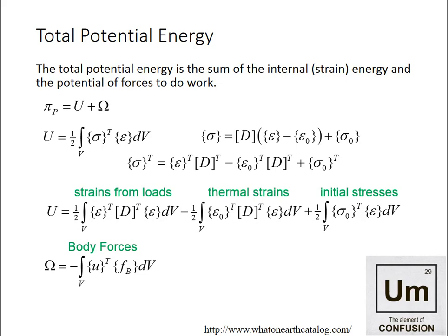What I'm going to do is break the forces into 3 different components. So the first one I've got showing here is the body forces. So I've got my expression for the displacement field multiplied by my body force vector, and then I integrate that over the volume. I also want to consider forces that might be acting on the surface of my body, or surface tractions. So similarly, I'm going to have the displacement field on the surface, multiplied by the surface traction. So the distinction between these two terms are integrating over the volume, integrating over the surface, and also that body forces are force per unit volume and surface tractions are force per unit area.